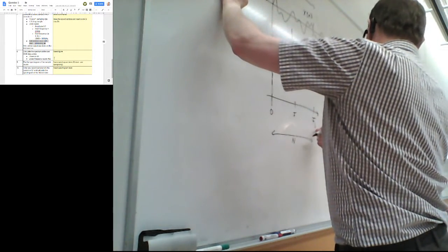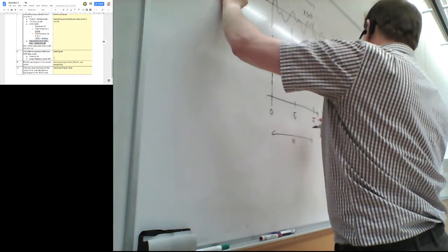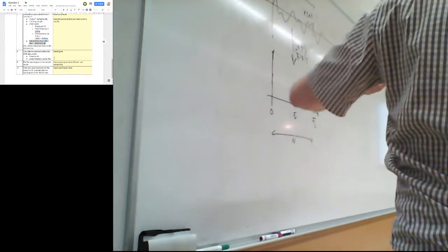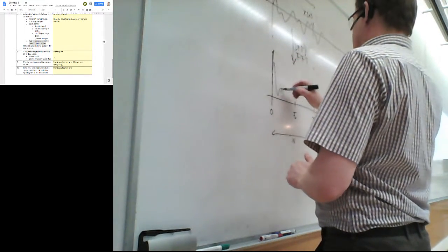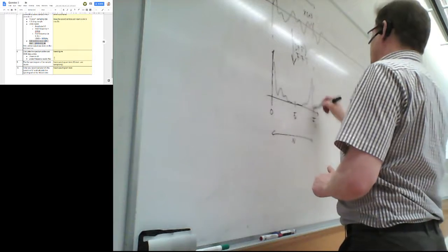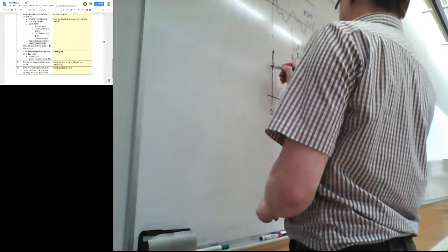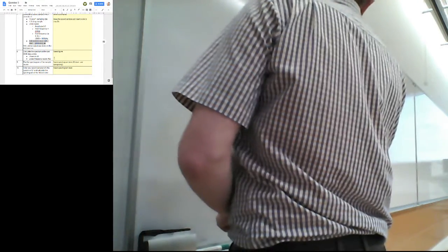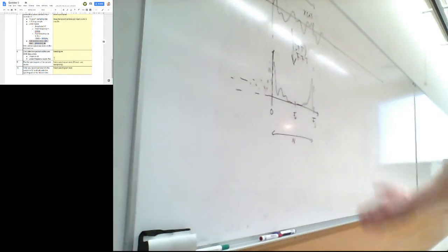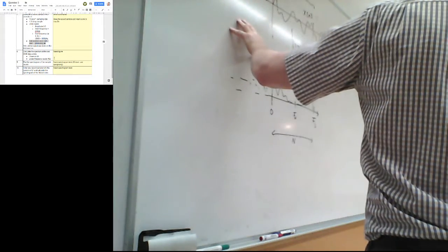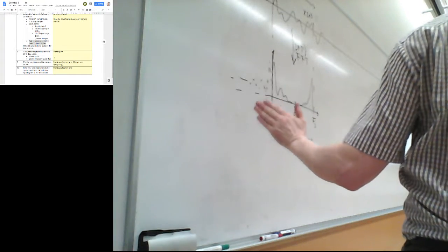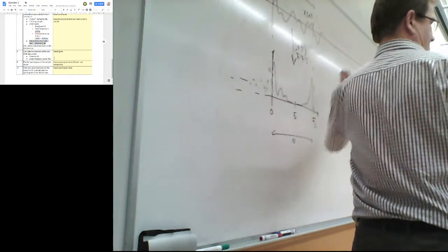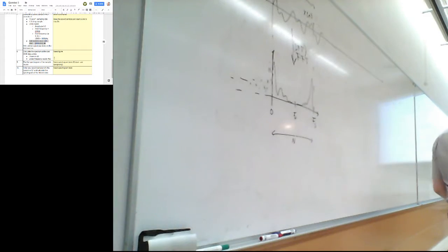And there's something funny. That part is above the Nyquist frequency, but you need it because it's the negative frequencies. In principle, the spectrum of a discrete sample is periodic.